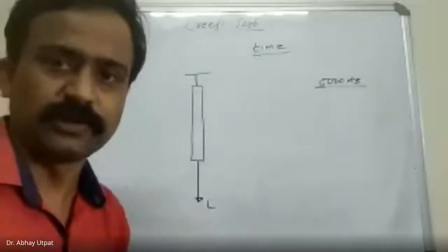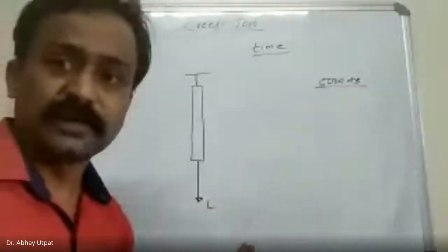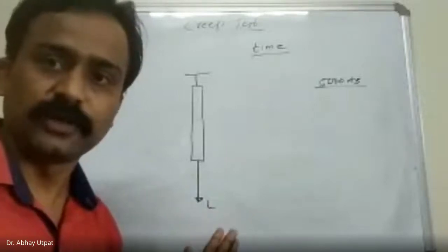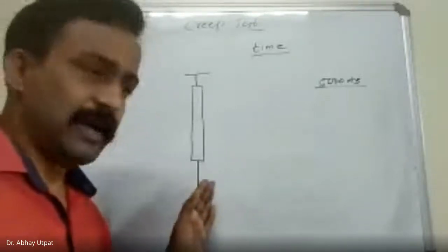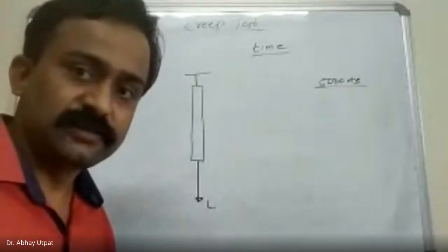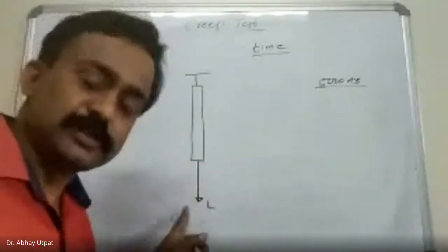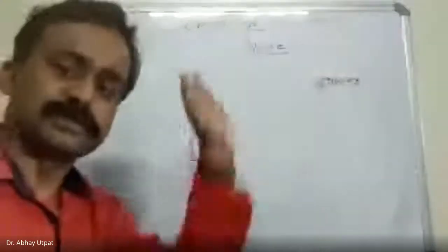Just check on the calculator. So it remains there for almost 6 months. Means at 50 degrees Celsius, this specimen can sustain this load for 6 months.